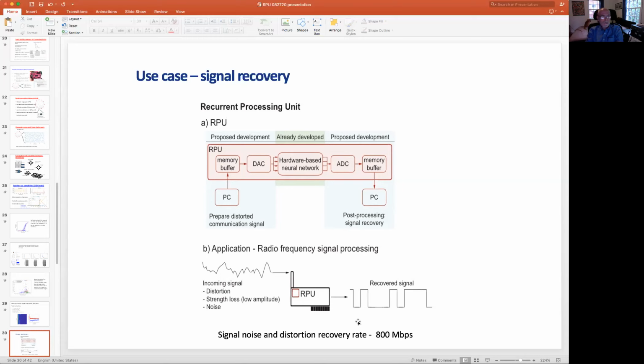The first one we did was a machine learning task of cleaning incoming serial data. The data has nonlinear distortions and signal loss, so that is noise that is added into it. And we trained the FPGA to reduce the distortion and noise for a recovered serial signal, and we do that on a large sample of distorted signal where we know what the recovered signal looks like, to then compute the output vector.